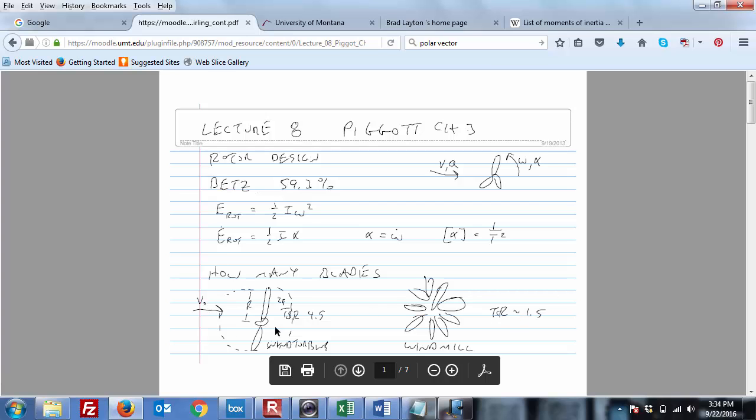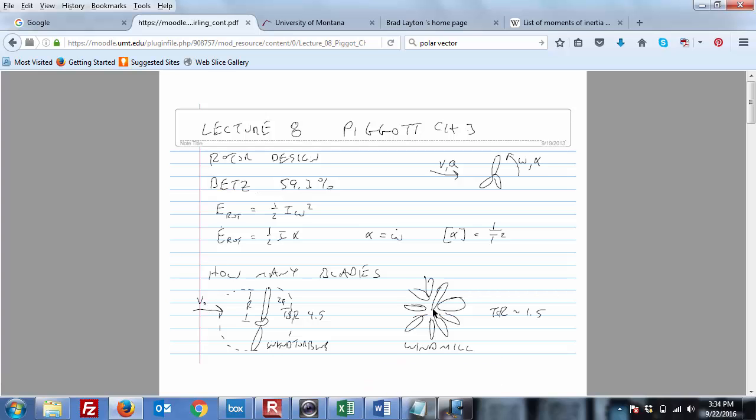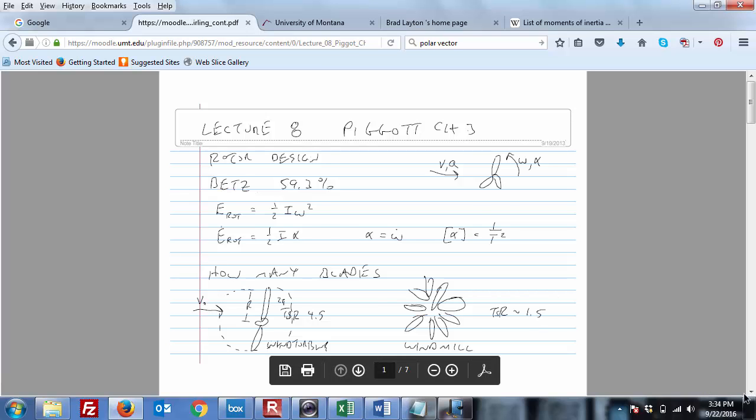This guy is higher speed, this guy is higher torque. Right, 'cause it goes slow. High speed, high torque, yeah. Might be the same power, just as powerful, but just think of your car accelerating in first gear trying to get up a hill with lots of torque, lower RPMs, versus speeding along the highway, relatively little torque, but higher RPMs and a lot more drag. But could be the same exact power.